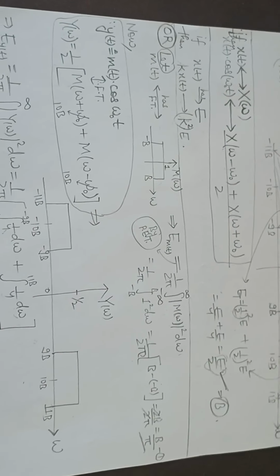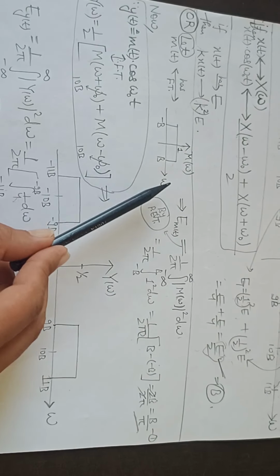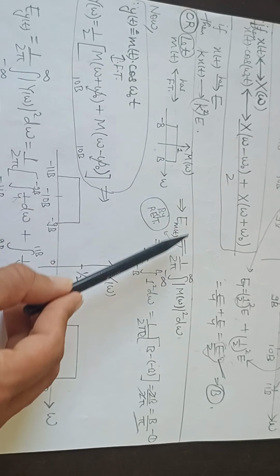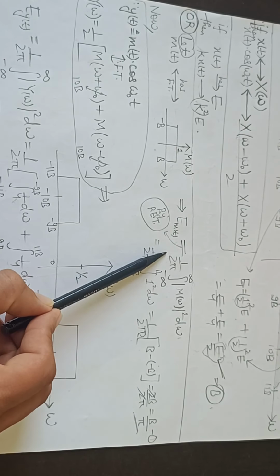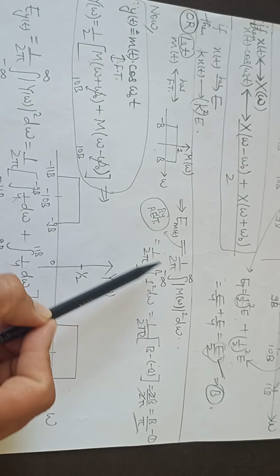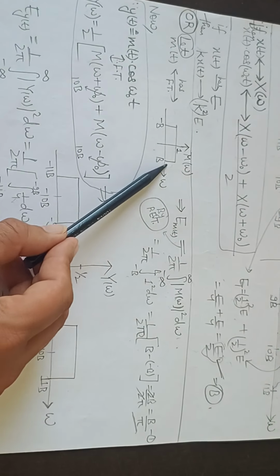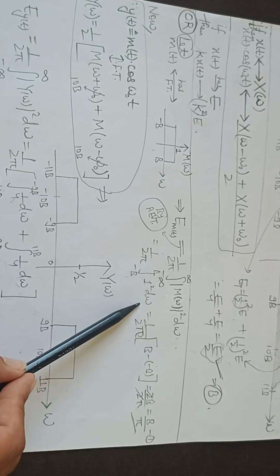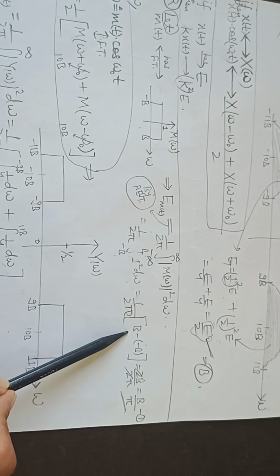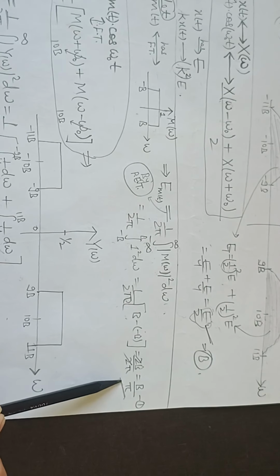Or what you can do is, let m(t) have this Fourier transform, from minus b to b, since it's band limited. So energy of m(t), using Parseval theorem, will be 1 upon 2 pi, integral from minus infinity to infinity of |M(omega)| square d omega. So this is 1 upon 2 pi, integral from minus b to b, and amplitude is 1, so 1 square d omega. So this is basically 1 upon 2 pi times b minus of minus b, which is b by pi.